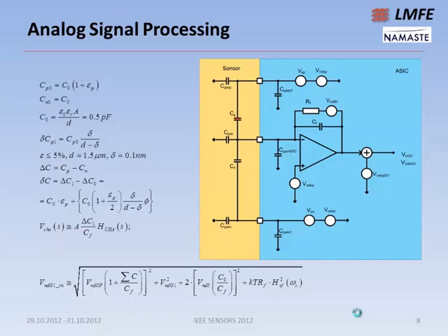The major contributor to the noise is, of course, this amplifier, because we were using a CMOS amplifier in order to really miniaturize and implement it in CMOS technology. And as you know, 1/f noise is a major enemy in this case, especially for low frequencies.